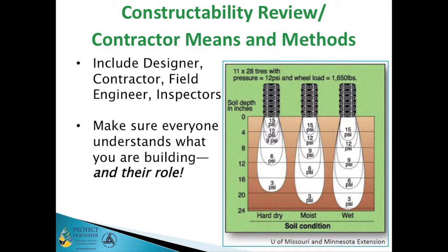Another example of this, one issue we often find, if we ask the contractor, well, let's wait and not build this rain garden until the end of the project because we don't want to get a lot of construction sediment into the soil there and plug up the soil so we won't be able to infiltrate. And so the contractor goes, oh, good, I've got a laydown area over here where I can park my equipment and do all this. And this is a